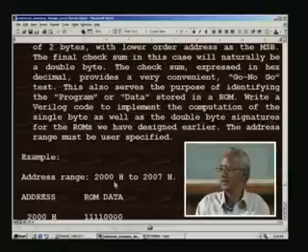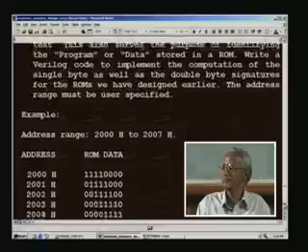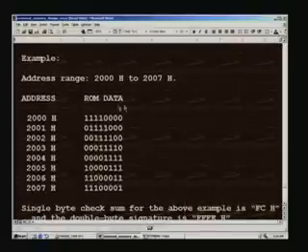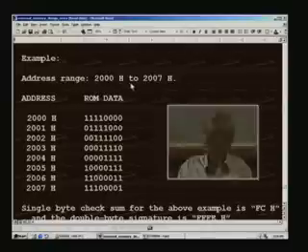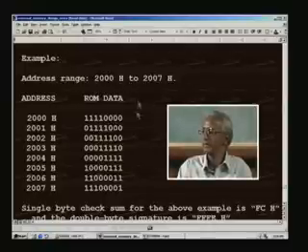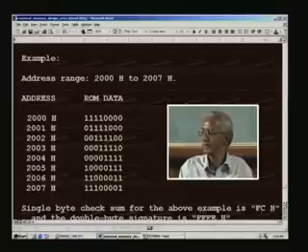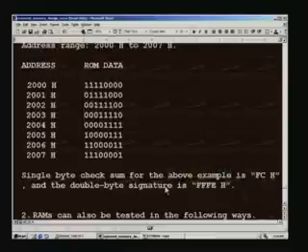For example, this is the address range the user will supply, and you will have to take this information as input and then compute the checksum we are going to explain now, and then report finally not pass or fail, but the actual signature. For example, if it is a single byte signature checksum, what we do is we add these 2 bytes and ignore the carry from this.